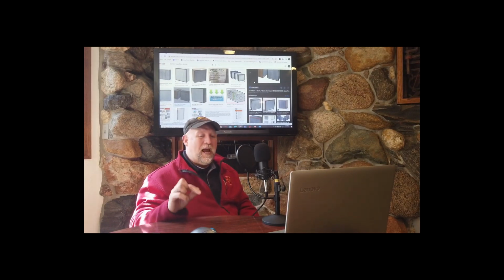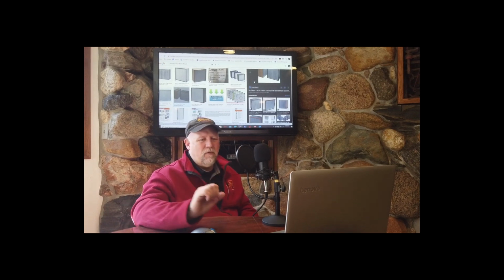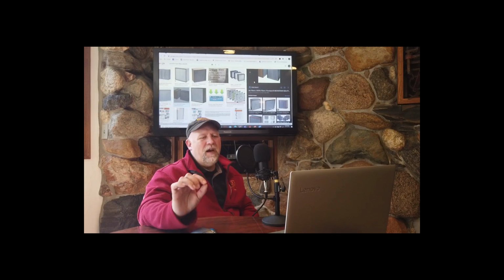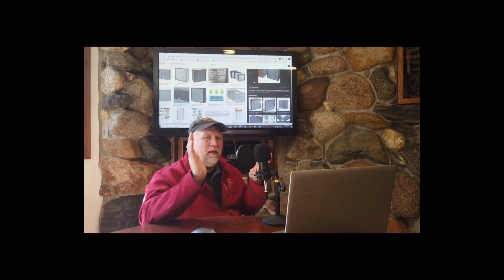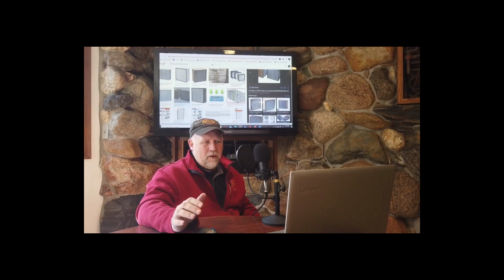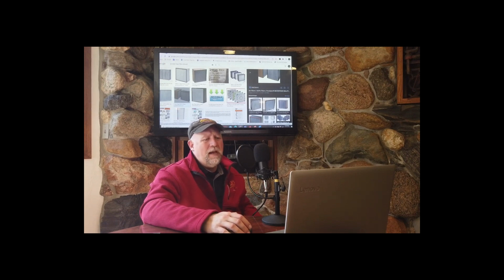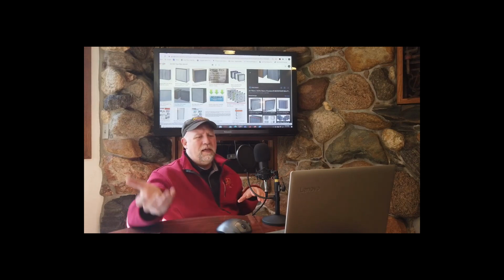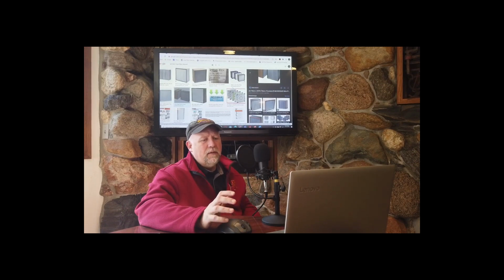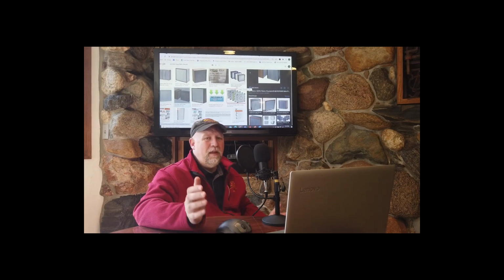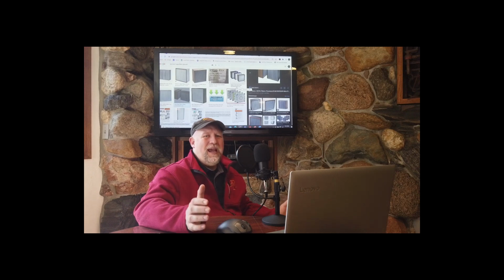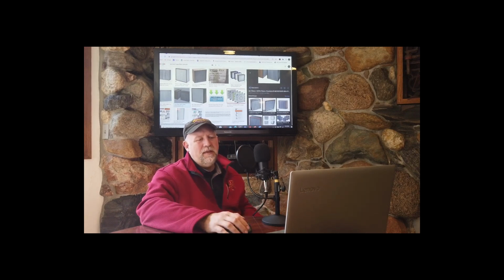And definitely in labs where we're doing experiments on diseases like that, also known as a biosafety level room, we're going to have very, very high levels of filtration, probably HEPA filters. In my career, I've only designed one room like that for the State of Iowa Hygienics Lab. They had HEPA filters on all the air coming into that lab and all the air leaving that lab. Grabs absolutely positively everything down to the germ level. But if you're dealing with infectious and deadly germs, it's the type of thing that you need.